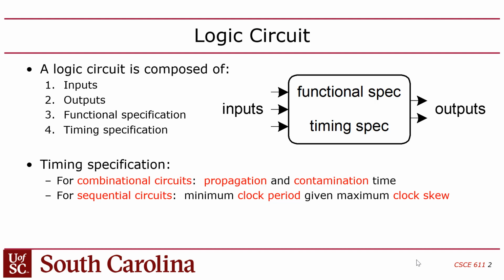Okay, so when you simulate in Model Sim, you guys haven't had to worry about timing. Delay, I should say. You've had to worry about timing in the sense of clock cycles, right? You have to synchronize things to clock signals. But every time you have logic, the output changes right after the inputs change, right? There's no propagation delay between the inputs and the outputs of the logic circuit, right?